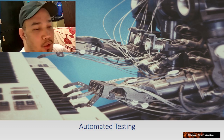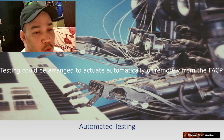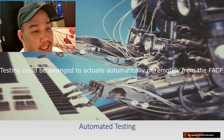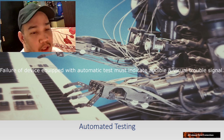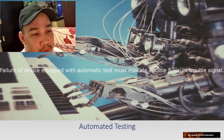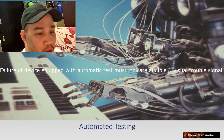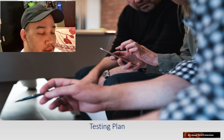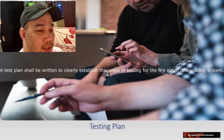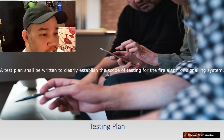NFPA 72 permits the use of automated testing arrangement. The testing operation could be arranged to actuate automatically or remotely from the fire alarm control unit. Failure of device equipped with automatic test must indicate audible and visual trouble signal. Test plan: a test plan shall be written to clearly establish the scope of testing for the fire alarm or signaling system.